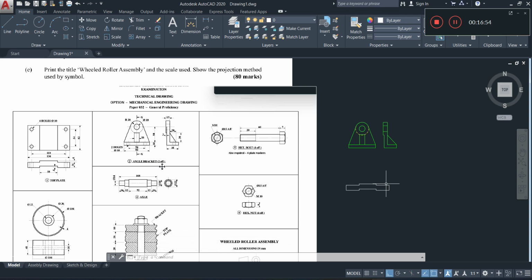Alright, and in terms of the hole, from the sectional view perspective, you would not see it because of the cutting plane. It's not in the cutting plane path, because it's off to the far right and far left. Alright, and the cutting plane is running right through the middle, so it means that we wouldn't cut through the hole. Alright, so let's go ahead and add this to our object layer.